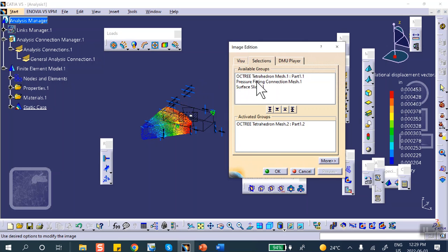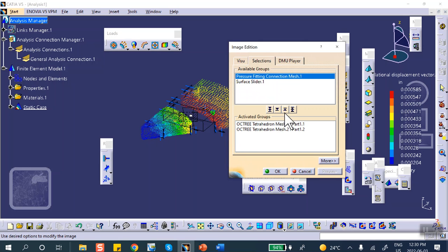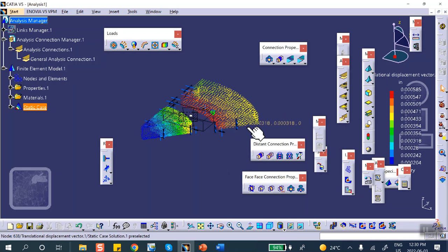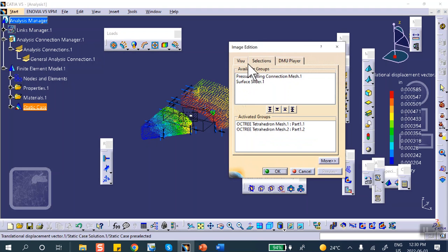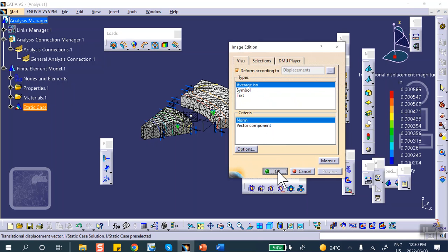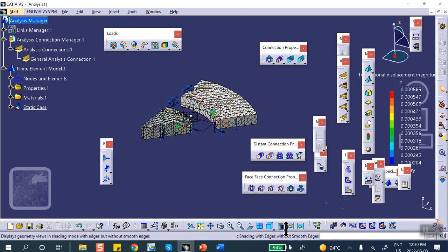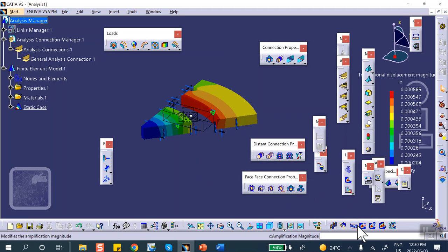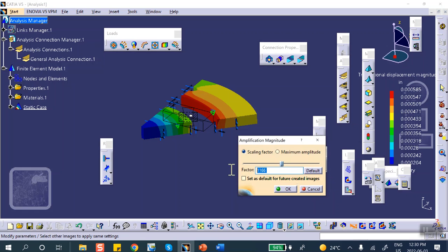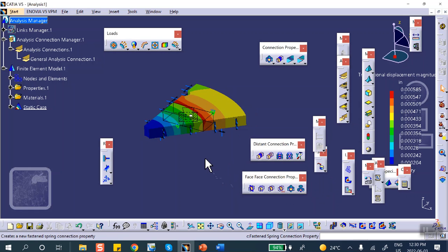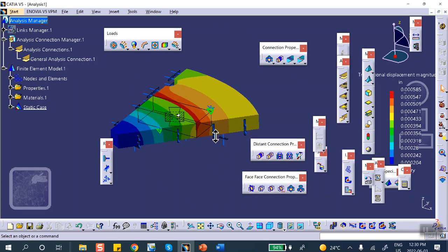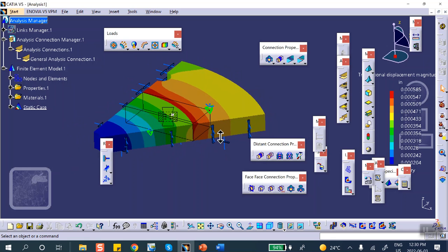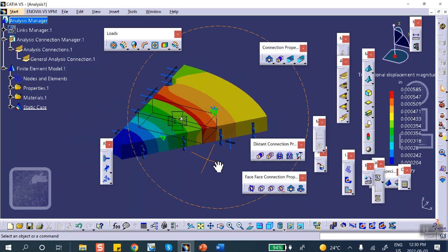If you look at the deflection, again, if you want to see only the elements that you maybe care about, get rid of those, and if you want, you can change it to average ISO and change it to material shading. There we are. The scale, set it to 1 so that you don't see that gap. That gap is not physical there. Okay. What is this? Translational displacement.